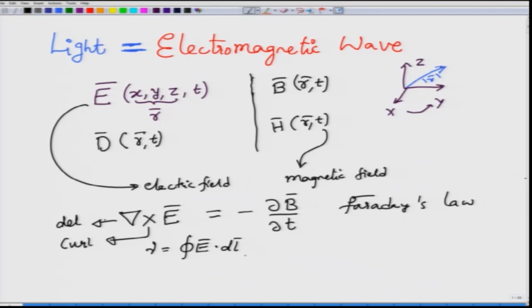This is your familiar KVL equation. So, there are no sources, the magnetic field is not changing, and as you pass along the loop, you would see that the total EMF induced would be 0. There might be some elements where the EMF is increasing, but there will be some where the EMF is decreasing, with the net result that in the static condition the EMF will be equal to 0, but not so when there is a magnetic flux.